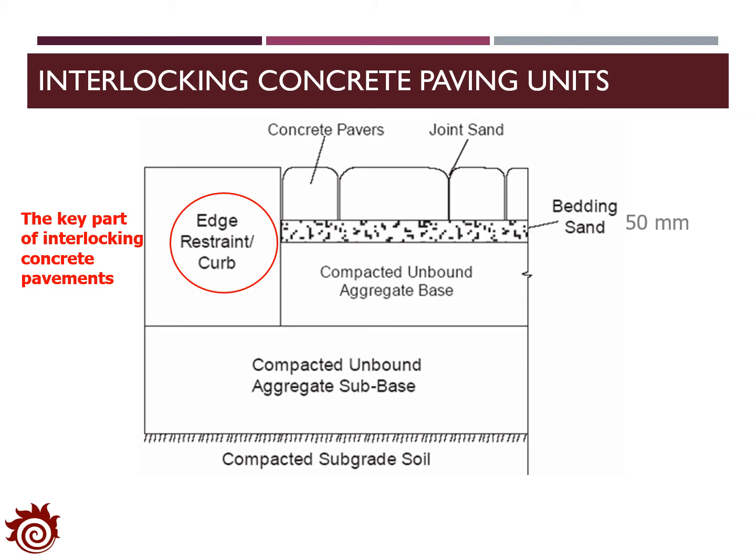This pavement also introduces a new layer, the bedding sand layer. Usually the depth of this layer is around 50 millimeters. This layer is not compacted very well before laying the concrete pavers, but it will become compact very well after the units are all placed. So the materials for bedding sand should be selected carefully before the pavement is constructed.